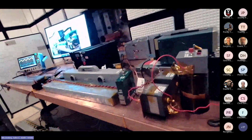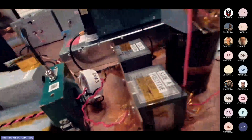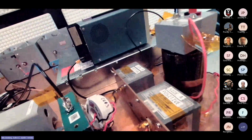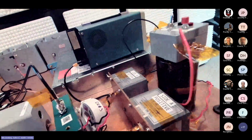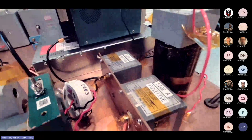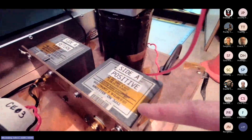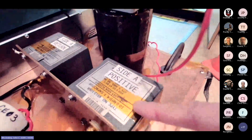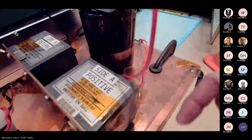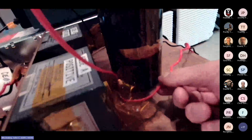And the next best thing to putting a real battery here is to put a lot of capacitance at the distribution point. So the older versions of MIL-STD-461, up to MIL-STD-461C and 462, used a pair of 10 microfarad feed-through capacitors, and they're exactly as described. They just feed the power through the capacitor.